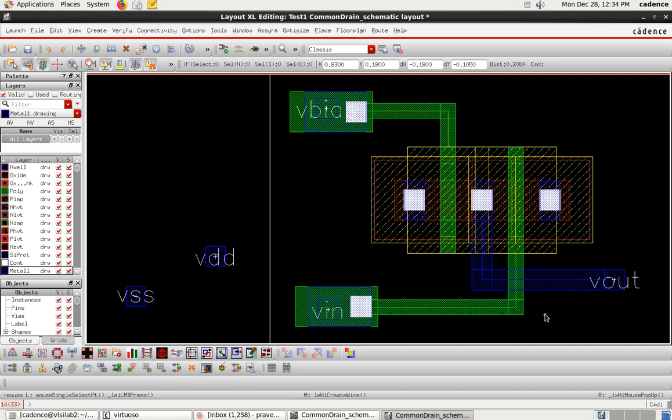So if you ask me, why are you passing polysilicon or metal on polysilicon? You can pass it, right? There is no problem with passing the metal on the polysilicon. That will not create an overlap unless you place a contact here. Via contact, if you place it here, it will connect, otherwise it will not connect, right? So we have a free move around this direction. So I've just connected it.